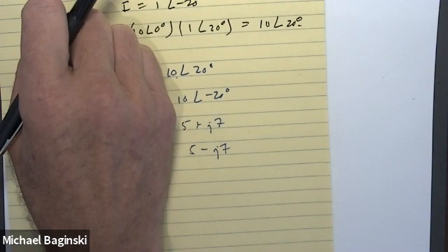Now, this is akin to, if you think about it, the sum of all the voltages around a closed loop being 0, or all the currents entering a node equaling 0. Whatever goes into it comes out of it. It's the same principle. And it's really a principle of conservation of energy. In this case, it's conservation of complex power. It's energy per unit time. Are we good on this, class?